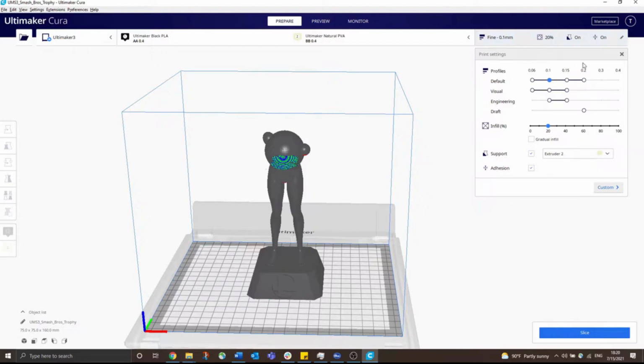And then these numbers to the right are your print resolution, also called your slice height. These are in millimeters, so anywhere from 0.06 millimeters to 0.2 millimeters. You can choose these circles, which are your available model heights. Okay. The next thing is your infill percentage. I believe the Stratasys tutorial already covers this, so I'm going to go briefly. Infill percentage is pretty much just your print density, if you will.